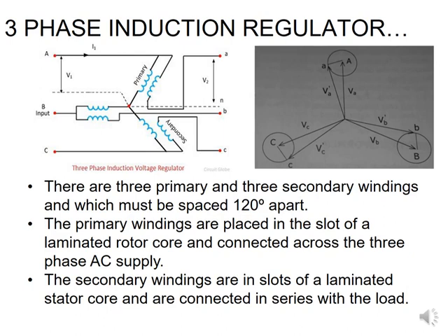So what this boosting wants to do is take your small a, b, and c and increase them in voltage such that they can equal the voltage that was on your supply side. And that is what you see in the circles. The circles are showing that this will boost your voltage V'A to be the same as VA at the end, and the same with your B and C phases.